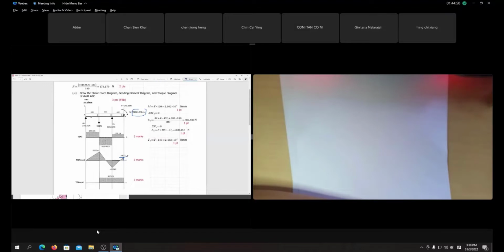Okay, along the shaft ABCD, which one is the critical point? B or C? Yeah, since B have the greatest moment value. But do not ignore negative value. Sometimes the negative value, even is on negative side, is bigger magnitude than the positive. Be careful about that. You have to be aware of that. Okay, tapi in this case yang inilah 52 ni is greater.